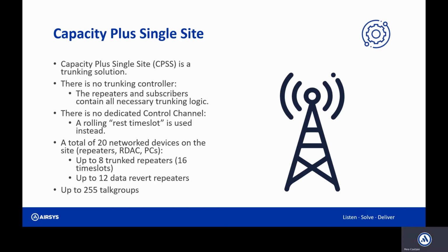You can have a total of 20 devices on the system. You can have up to 8 trunk repeaters, so that means 16 voice time slots and up to 12 data revert repeaters. And since this is a single site solution, you cannot connect this to any other sites. You can only have one site. And you can have up to 255 talk groups.